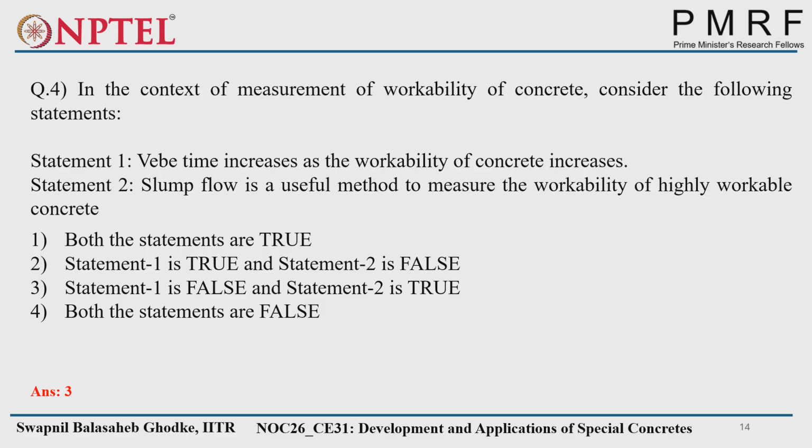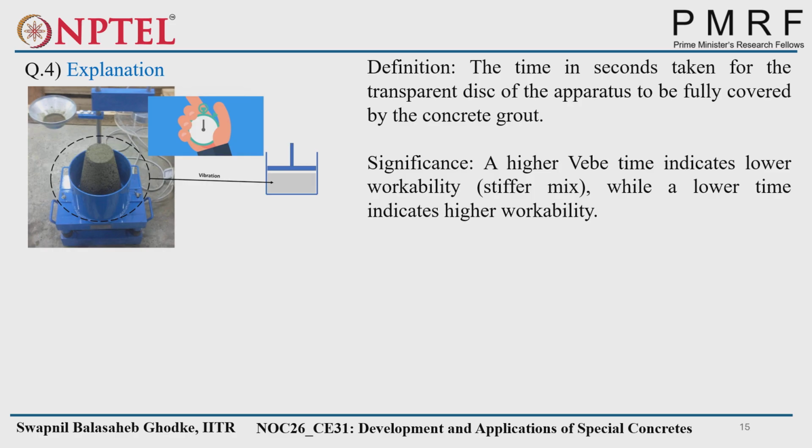Slump flow. Everyone knows about the slump test, right? Slump flow uses a similar method, but we measure the flowability of the concrete on a platform. And the statement that VB time increases as the workability of concrete increases is wrong, because as the VB time increases, the workability of concrete is less.